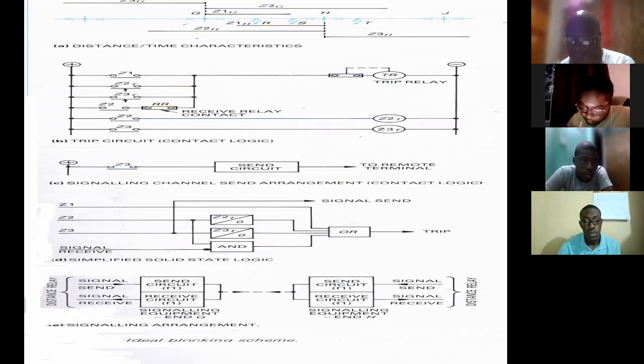So it is in zone 3 for H and it's in zone 2 at G. So would I have the instantaneous contact for zone 2 closing? Which relay? So you're talking about H, right? No, man. Remember, the fault is at T. And we're looking at G. Remember, what's the objective? The objective is to clear the fault on the line.